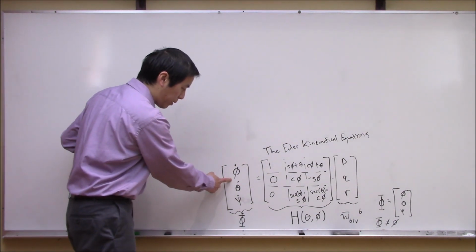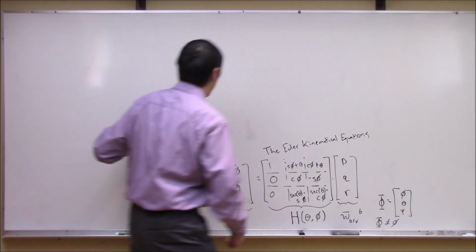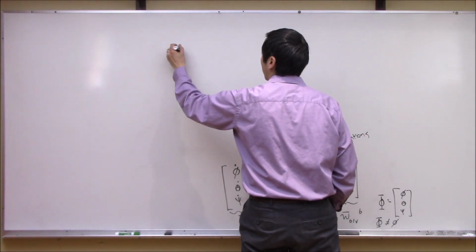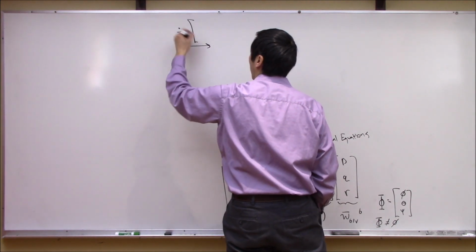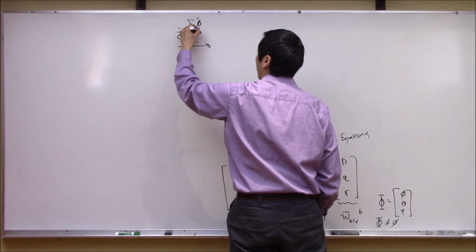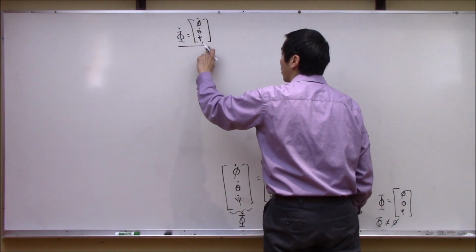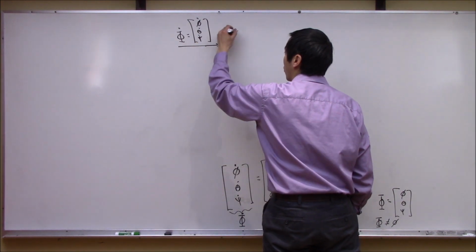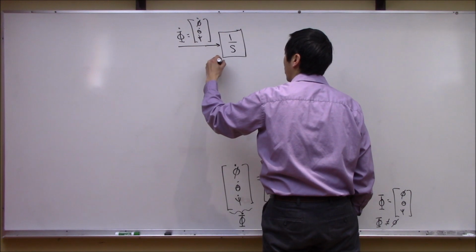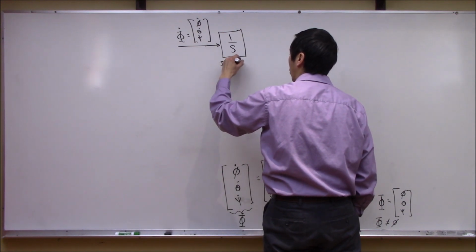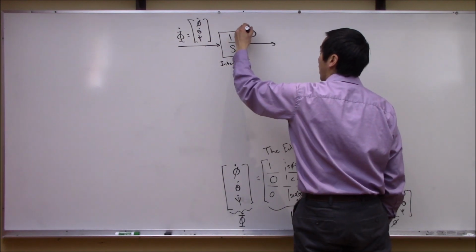So the first thing we should maybe start with is let's get the signal phi dot, right? Let's say that you're able to generate this signal, capital Phi dot, which was the rate of change of the Euler angle. So it's phi dot, theta dot, psi dot, right? Okay, well, if we have this signal, probably the easiest thing to do is run this through a numerical integration scheme. So I'll write 1 over s, here's our numerical integrator, right? So you integrate capital Phi dot, what comes out of this is just capital Phi, right?